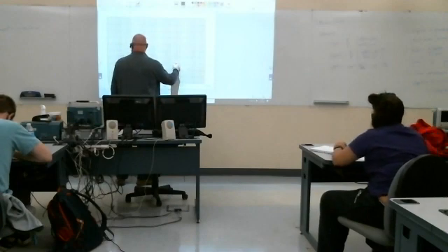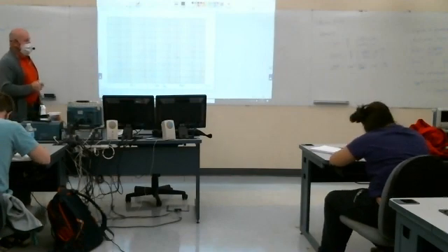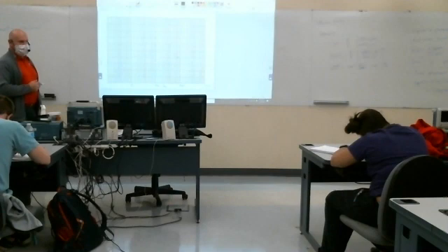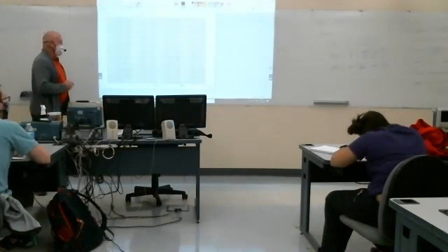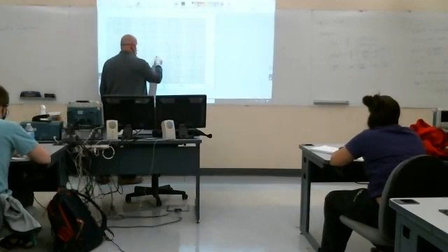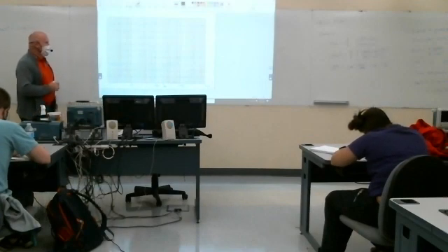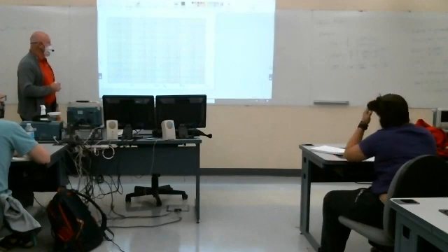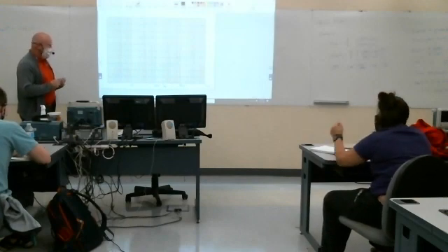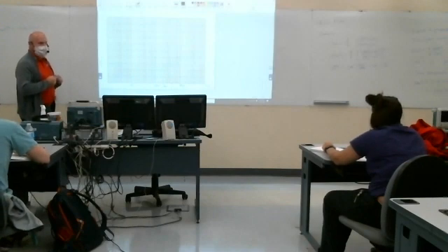Here's my 0 dB line. I'm going to mark that with a circle in the numerator corresponding to a zero frequency, because it's in the numerator. And then the one in the denominator is at 1,000, so I'll mark that as an X. Okay, any questions about that?